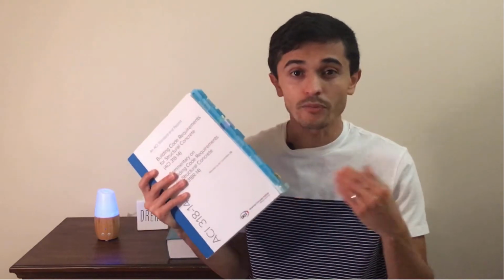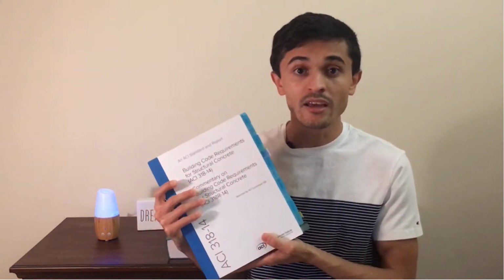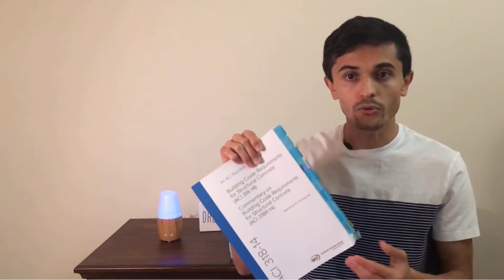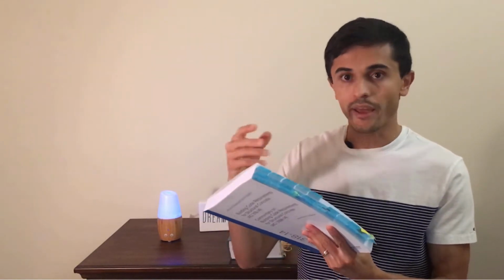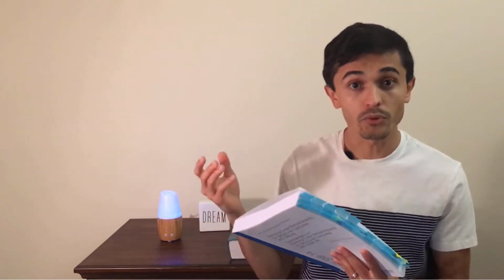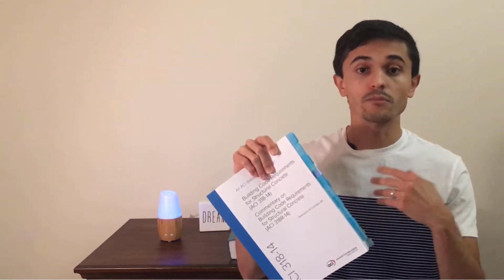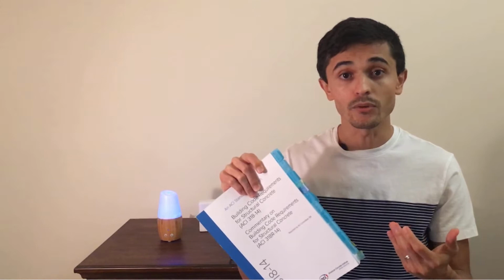Just because the company has ACI does not mean that I'll use it as much unless I actually dig through it and see what's in it. So just by knowing where to find rebar diameters or where to find minimum reinforcement ratios is really helpful. And because I have the tabs and because it's easily accessible, I can go there in a matter of seconds and find the information that I need. Those are my top 2 books or manuals that I use on a daily basis that I have tabbed up.